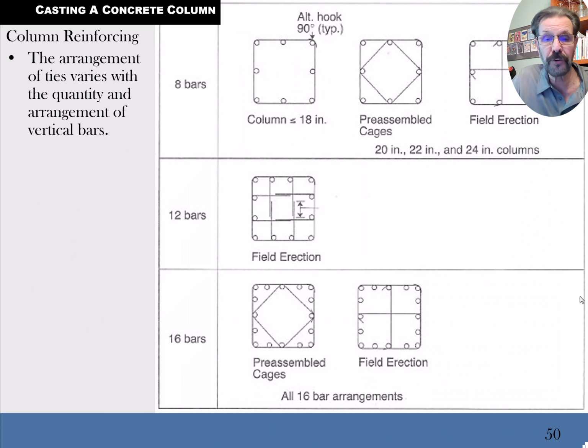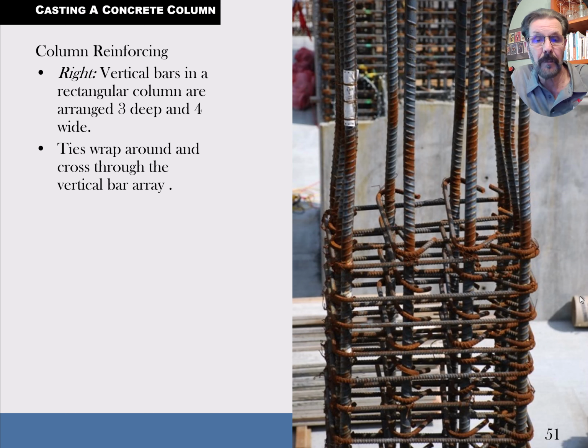There are various versions of the patterns in the concrete column depending on the size and what the forces are. Sometimes you can get so much steel in a column that it gets pretty congested, so you have to pay attention to what kind of concrete mix you're supposed to be using with that column. You may have several concrete mixes on your drawings, and you have to make sure that when you're pouring concrete for this column, you're using the column concrete that was specified for it.